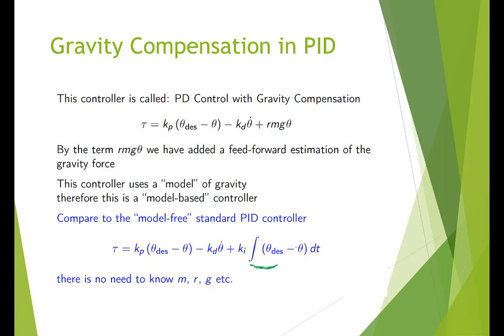So we have the option to use this gravity compensation, where we cancel out the gravity terms, or to use an integral. Both of them work. It's up to us to pick which one for a specific type of controller. So this was an introduction to PID. What is a PID controller? And to summarize,